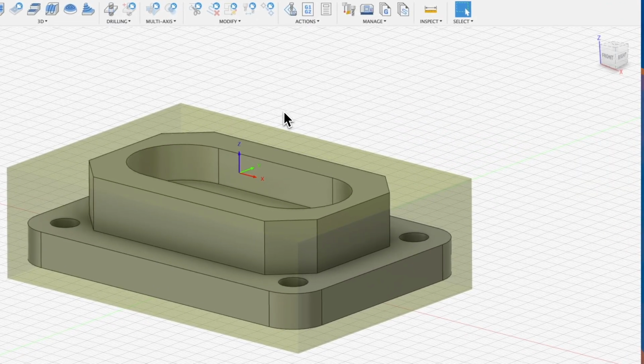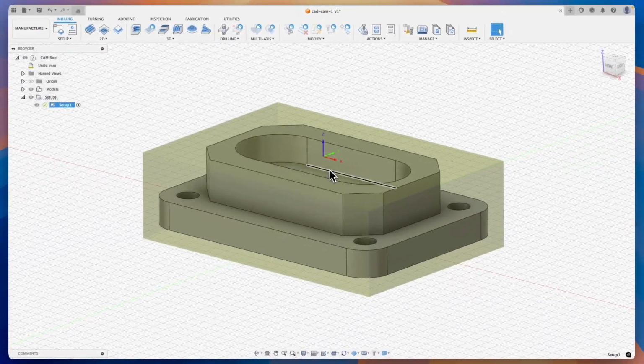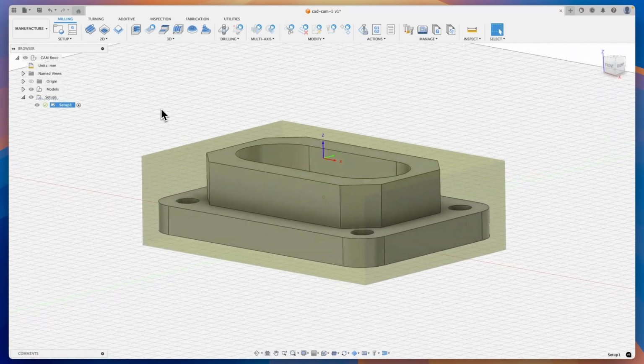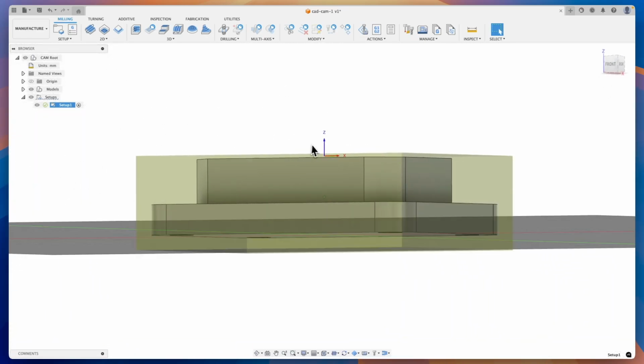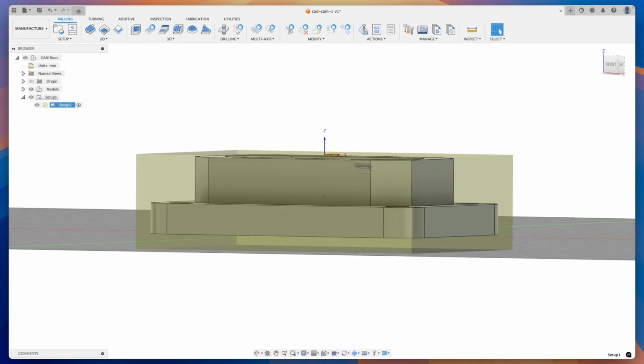This is the coordinate system relative to which the toolpaths will be calculated and the machining program will be generated. Therefore, on the CNC machine, the coordinate system should be placed in the same location, as the program we prepare in Fusion will be executed based on this coordinate system. The first machining operation we will apply here will be the facing operation, which allows for the quick and efficient removal of material on the top of the part.